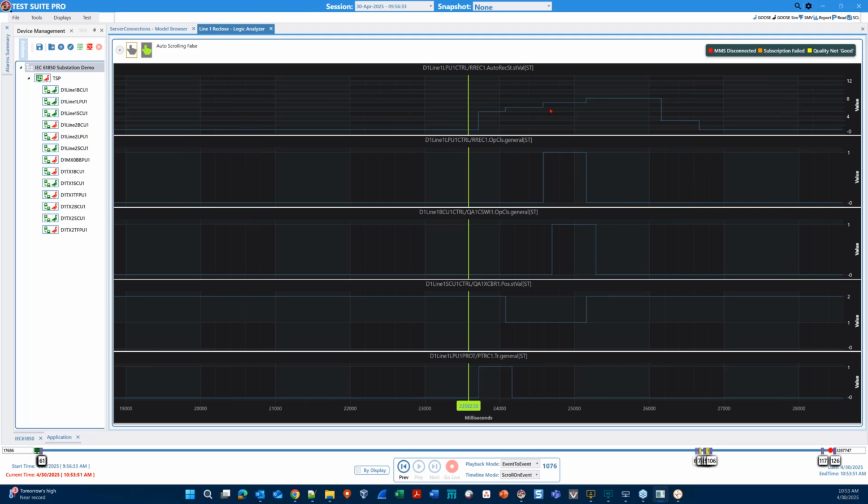And then from there, we moved into in progress. That was basically a waiting period to see that the fault would continue to remain cleared, I'm sorry, continue to be disappeared, while the recloser does its job and issues the reclose attempt. A short time later, the breaker does actually close, and then finally we move into a successful state. Once that final timer expires, we're now ready. We can return back to a normal state.